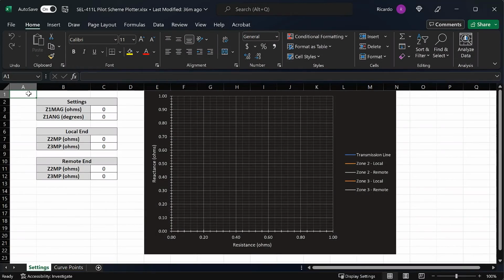So let's take a look at the impedance plot for this example. All right, so here let's use the positive sequence impedances only. I'm going to be focusing here on the phase elements, although a similar process would apply, of course, for the zero sequence impedances for ground faults. And here I'm also going to be using the primary impedances. Just know that, of course, if you were to enter these numbers into a settings file, you would need to convert all the impedances to secondary impedances, as opposed to primary impedances. But just to keep things simple, I'm going to use primary impedances.